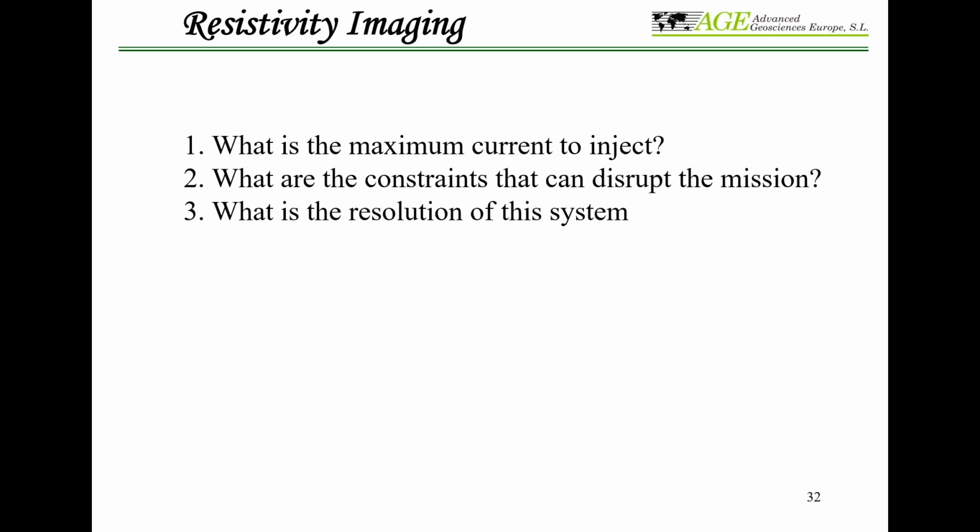But part of the difficulty is data acquisition in a heavy wavy marine environment. If there are lots of waves while you're pulling your cable, some electrodes may be in the air and some in the water. That will create noise.